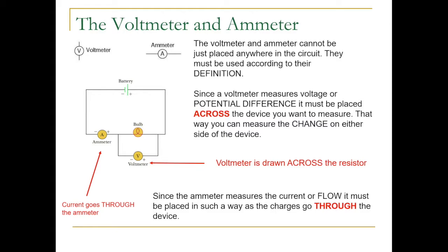Now there's some important theory to consider when we're talking about ammeters and voltmeters when it comes to the idea of resistance. If you think about what an ammeter is supposed to do, it's supposed to read the current by allowing it all to flow through. Well, it wouldn't make much sense in theory if there was some resistance associated with an ammeter. So when we talk about an ideal ammeter, we consider it to have zero resistance.